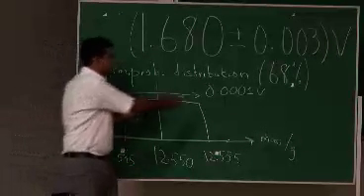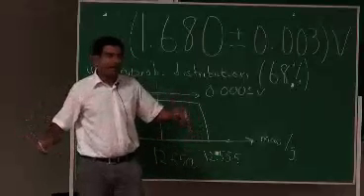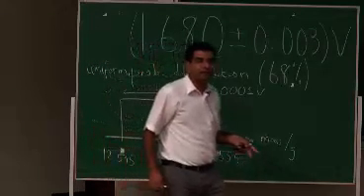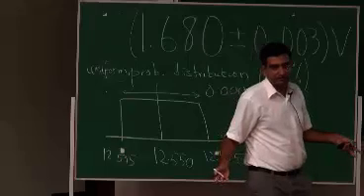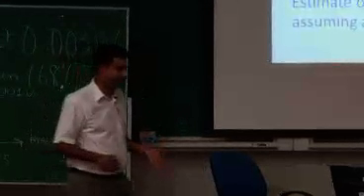So I can find this half interval and divide by root 3 because it's a digital scale. And this balance will also have some accuracy to it. So you will combine the type B uncertainty due to the scale and the type B uncertainty due to the rating of this instrument.